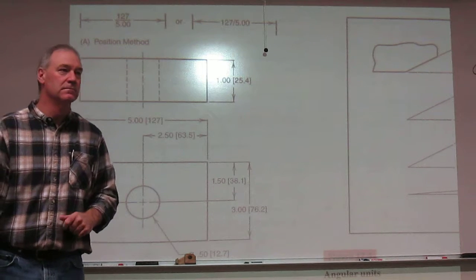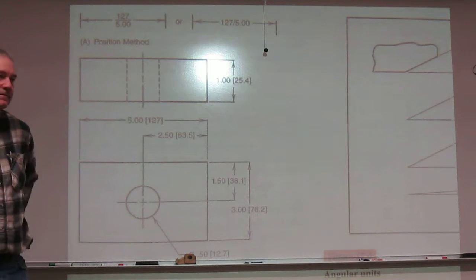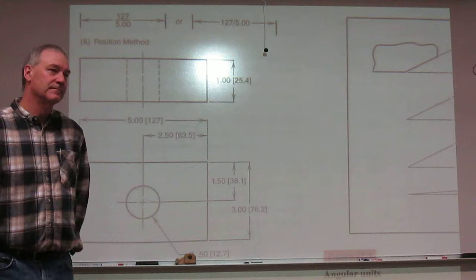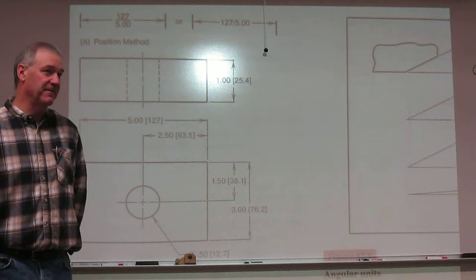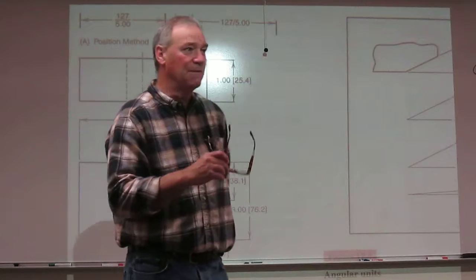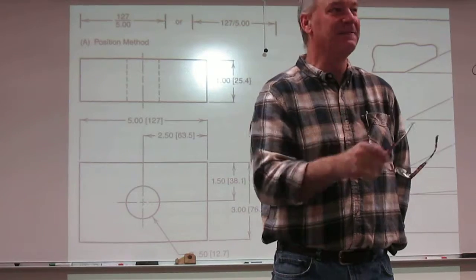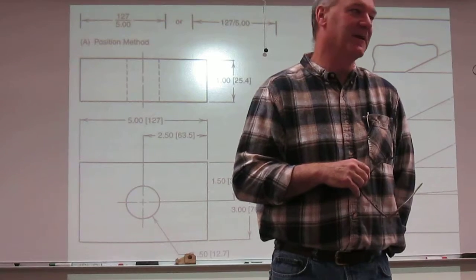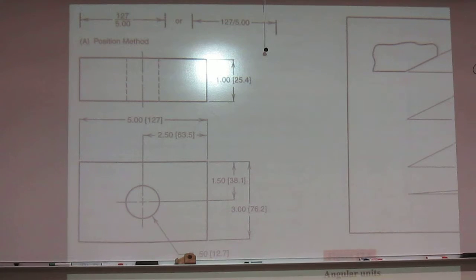Do they ever have situations where it's all in English, but then you have both options for the screws, metric or English? No, almost never. And the reason is that the threads are different. They are not equivalent. You can't go buy a 1-inch UNC, Unified National, which is our thread, and compare that to a 25 mm thread because they're different threads. They won't screw onto the same nut. Yeah, I've tried it and stripped it before. I think we've all done that.